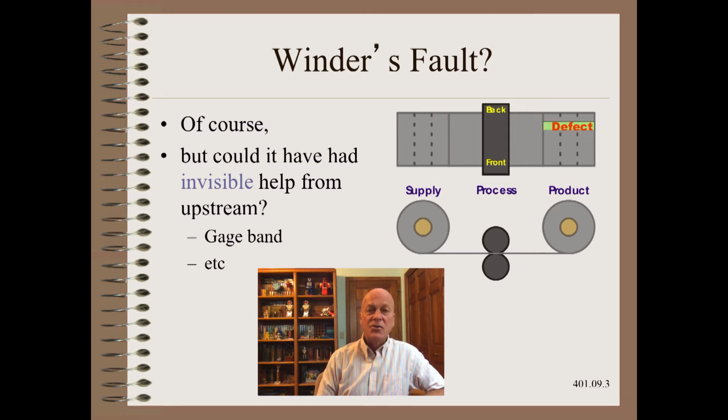Yes, you can and should wind looser, but that is not a strong knob and also has limits of its own. Thus, while we may start with winding tightness only because it is easiest, we will usually have notable success only by leveling the web.